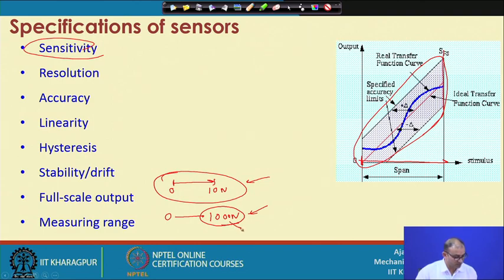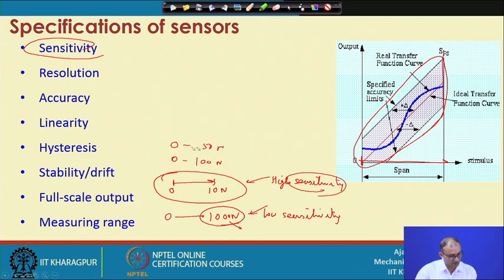For measuring 1000 Newton, if you make the system very sensitive, then sometimes you end up with garbage values. Those values are not important to you, and that is why when you are looking at a very small range at a lower scale, you can get a high sensitivity. But that is not the case here. Here you have to sacrifice sensitivity, because the same sensitivity cannot be achieved when you are looking at a very long range. So, you can go with 10 to 100 Newton or 0 to 50 Newton or something like that. In different ranges you can set different parameters.